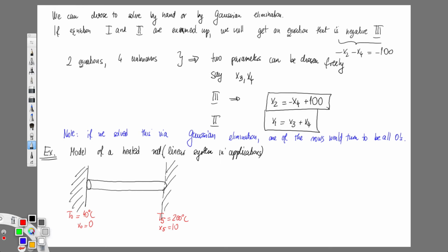My T ambient, TA, is ambient. It's 20 C. This is a rod, R-O-D, rod. So I have some heat transfer happening between the rod and the ambient. And basically how much heat I'm losing depends. There's a constant sort of transfer rate in between the two, but how much I'm actually losing depends on the difference between the temperature at a point and the ambient temperature. Okay? So that's what's throwing in the unknown.